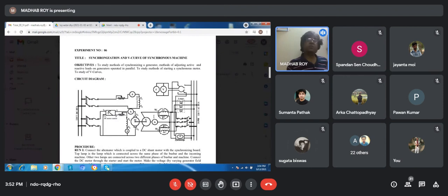Yes, sir. So in spite of the field circuit being off, and this field is a very soft field, because in a DC machine you don't have any permanent magnetism, since it is not desirable. So very soft type of magnet is used here. So we don't assume that any permanent magnet will act when the field circuit is withdrawn. However, this motor is running because it is neither having a connection from the rotor side, any mechanical drive. So it is running. That means it is running now as a reluctance motor. Got my point? Yes, sir.